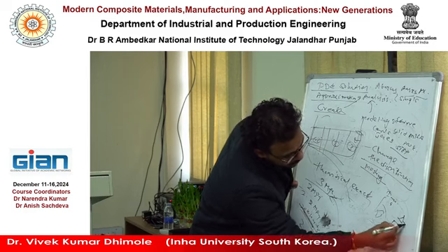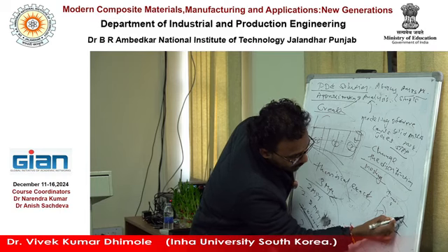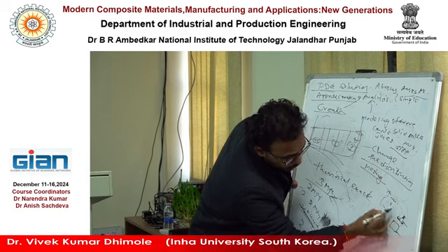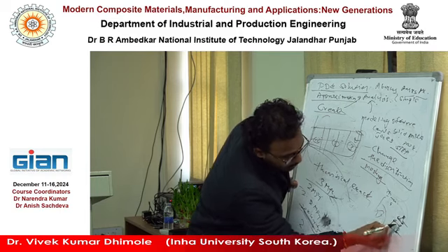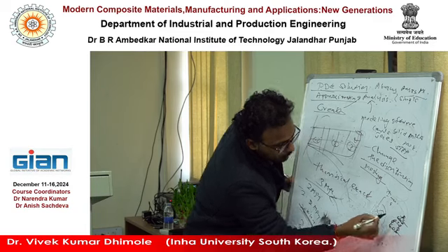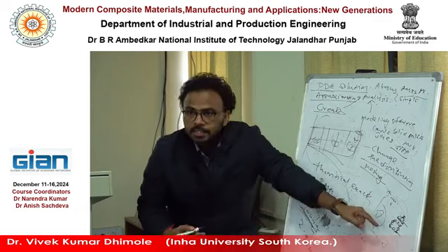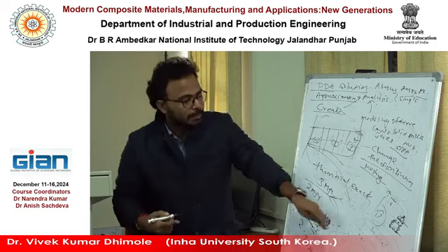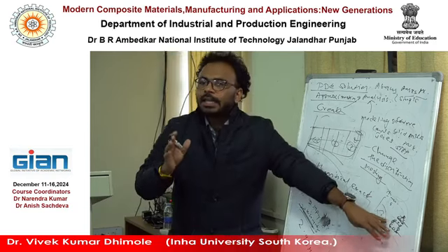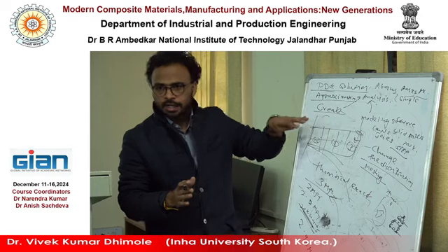In 2D, just 2 types of element, and in there also we have a first order element, with just 1 node like this. Second order element, we have a node like this here also. So as nodes increase, solution accuracy will increase because element order is increasing, right? That will take longer time to run because of large equations.